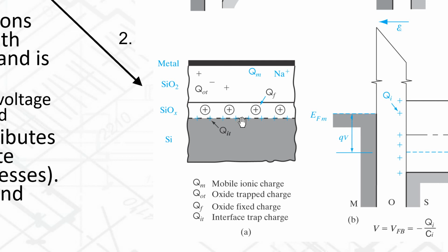Another thing that can happen is that the transistors on one side of your wafer have a threshold voltage of 1 volt, and the transistors on the other side of the wafer have a threshold voltage of 0.3 volts. So this could be disastrous if you're trying to put a billion transistors on a chip. So it was only when this problem was solved. In fact, nowadays, a lot of semiconductor processes use dry etching instead of wet etching to avoid this very problem.